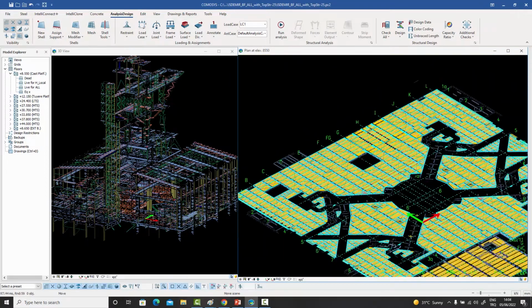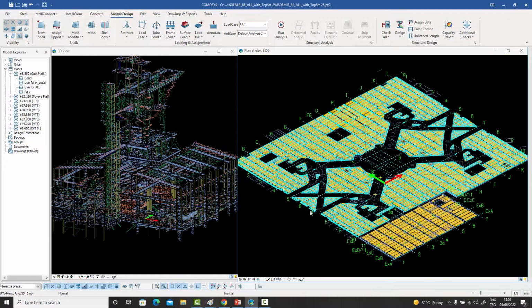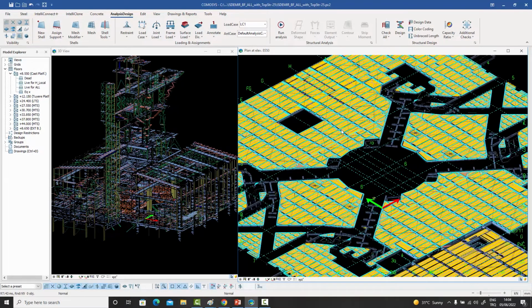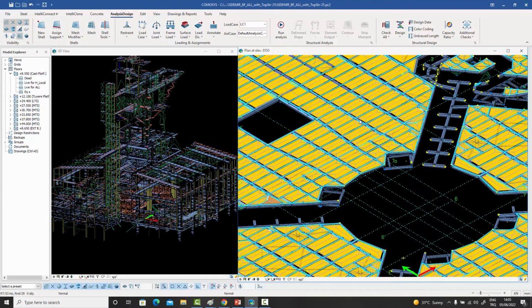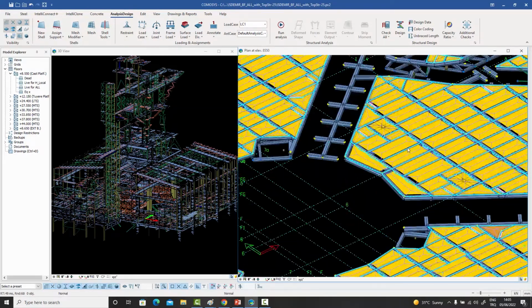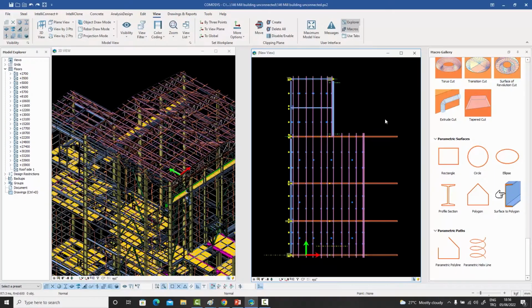So it'll end up as the same 10 tons which we wanted to give to the columns, and the columns will receive the total of 10 tons, and that will be transferred to the vertical braces and from there to the foundations. But the actual small moments which in real life do occur on these beams as M22 moments, for example, and all the loads in these horizontal bracings, etc., will actually be much more realistic if you apply the loads in this fashion.